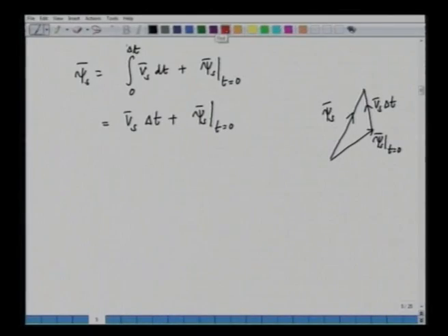and the third side is the stator flux vector, psi s. So, if you want to control the stator flux vector, you have to apply a suitable voltage vector Vs. This Vs can be in various directions, depending upon which voltage vector we choose. It can be one of the 8 voltage vectors, and 6 are non-zero voltage vectors. Accordingly, suppose this is my Vs into delta t. The resultant of this would be somewhere here. So, instead of this flux, I will have this flux.